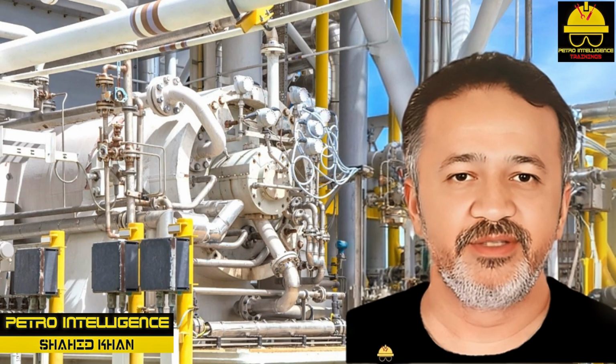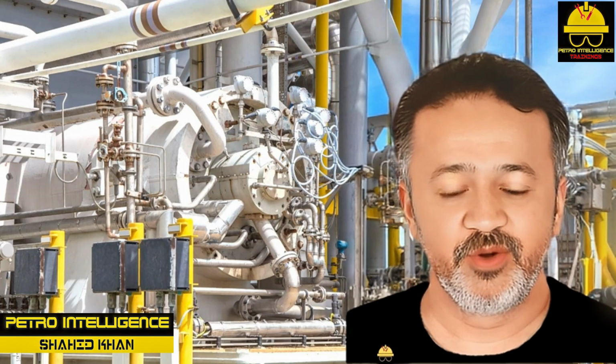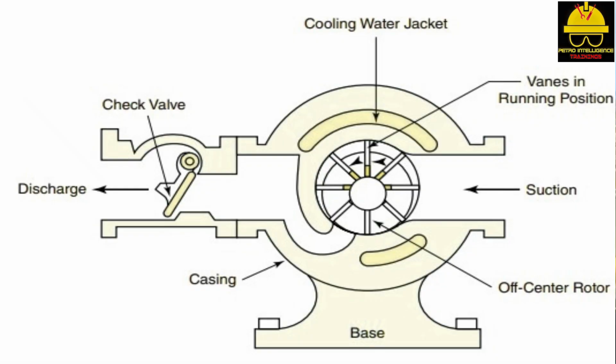Sliding vane compressors. The sliding vane compressor uses a slightly off-center rotor with sliding vanes to compress gases. The major components of a sliding vane compressor are shown in the picture. The gas inlet port is positioned so that gas flows into the vanes when they are fully extended and form the largest pocket. As the vanes turn toward the discharge port, the gases are compressed.